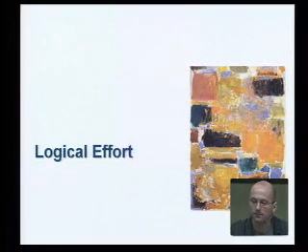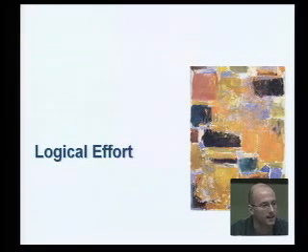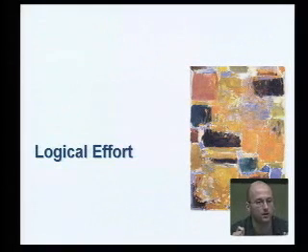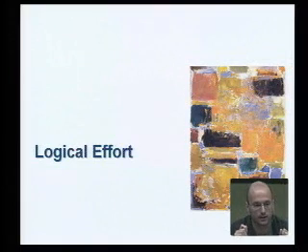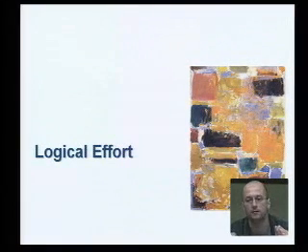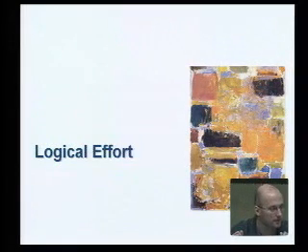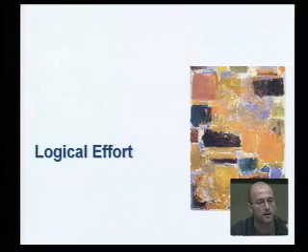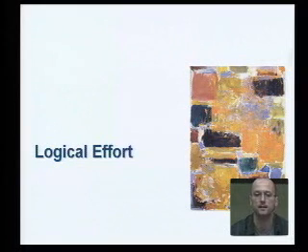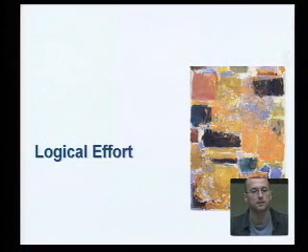And what this concept actually tells you is it compares the gates to that inverter and says how much, given the topology of a gate, for example, a NAND gate, how much more effort my NAND gate has to spend due to its complexity to deliver the same pull up and pull down as an inverter and make sure that I still have basically the same inverter-like performance. And that's called the logical effort. It's related to the logic function compared to an inverter, and it tells you how much extra effort my gate has to spend to be equal to that inverter.